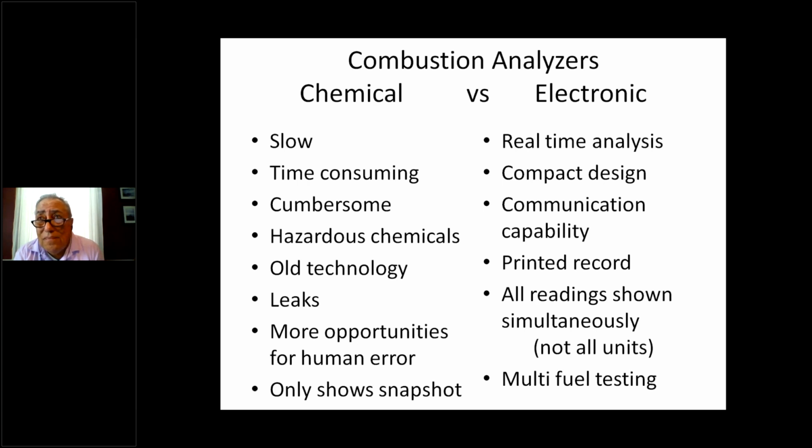Very good. And one last one from Avanish Ray. What is the best method for analyzing combustion efficiency, measuring CO2 percentage or O2 percentage? Either one will get you to where you're going to go. It depends on the analyzer you're using. Most of the analyzers today are measuring O2. In fact, a lot of the analyzers will give you both readings, CO2 and O2. One isn't any better than the other. They both get you to the same place.